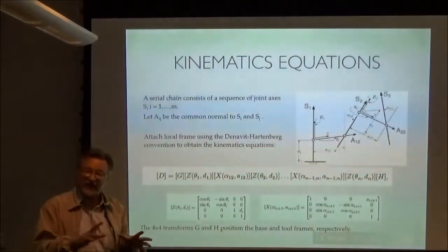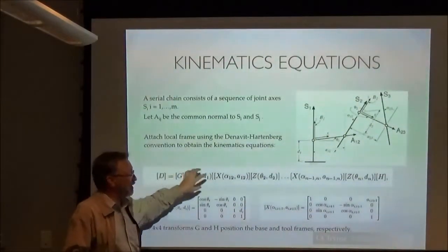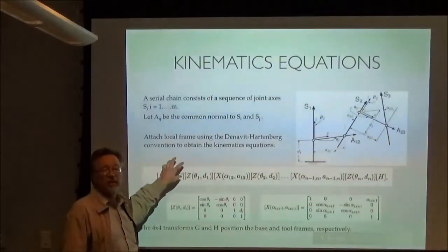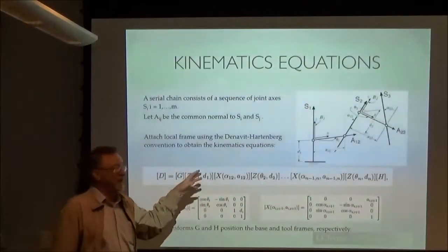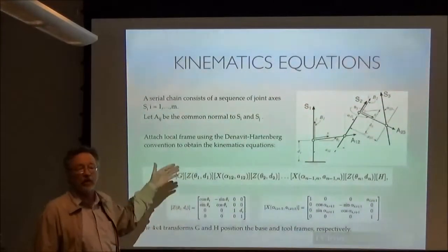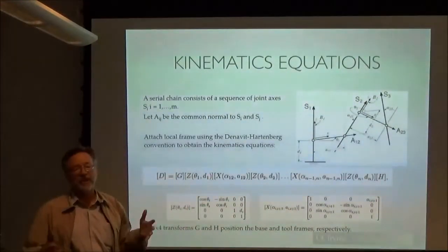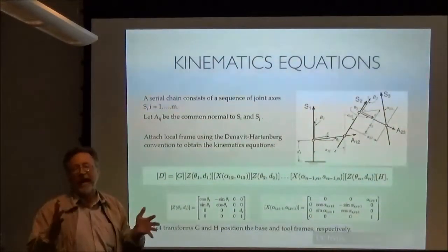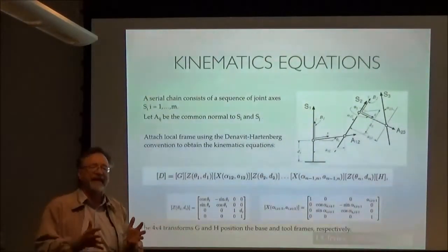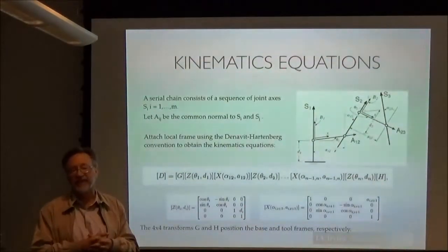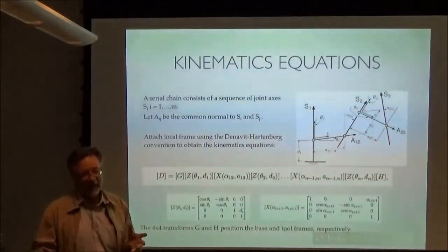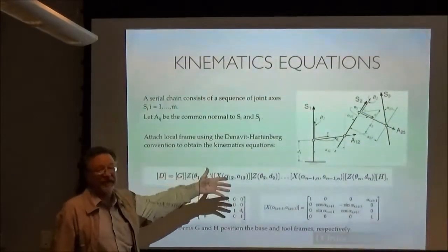So it actually takes a little bit of work to get from the Denavit-Hartenberg mathematical formulation to quaternions. That work happens to be going through the product of exponentials. So do not fall for anyone who pretends there's any kind of controversy in terms of the formulation of kinematics equations of the robot. There's not. All right, we all use the same basic form.